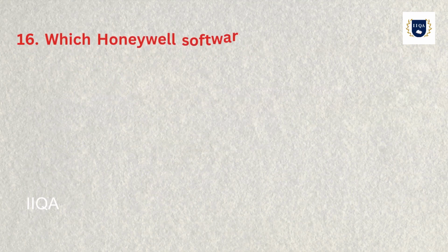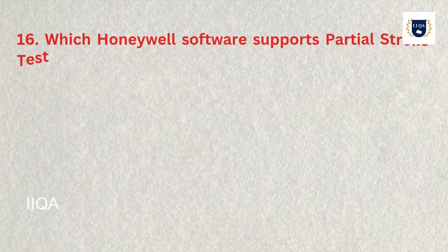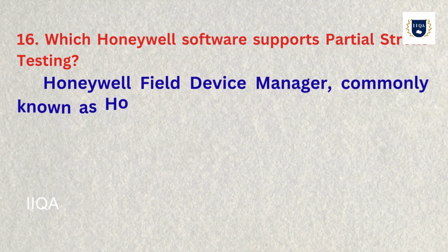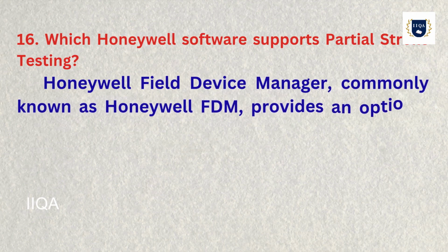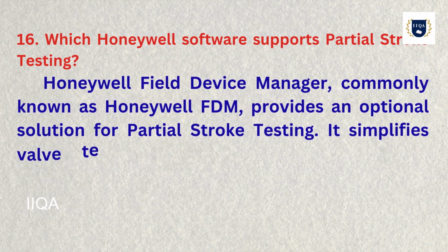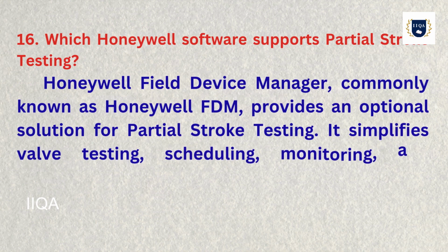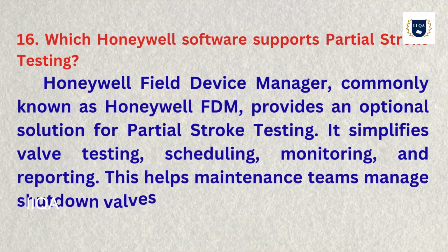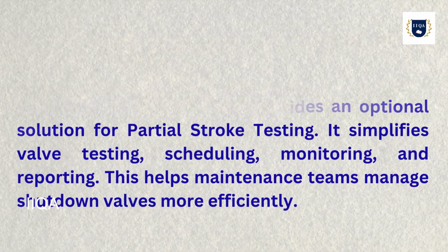16. Which Honeywell software supports partial stroke testing? Honeywell Field Device Manager, commonly known as Honeywell FDM, provides an optional solution for partial stroke testing. It simplifies valve testing, scheduling, monitoring, and reporting. This helps maintenance teams manage shutdown valves more efficiently.